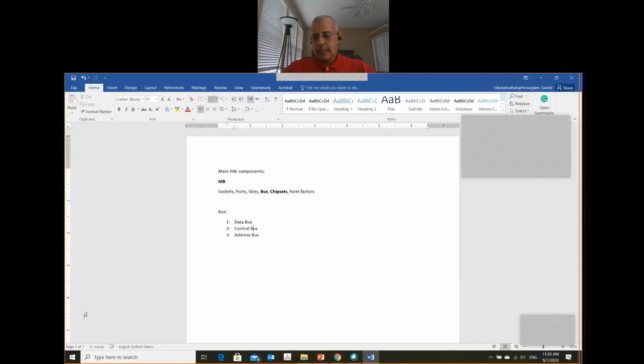Control buses, they define who can read from the bus. Suppose a bus as a kind of path between two cities. So it determines which end can read from this data line. An address bus determines where information should be sent, and defines the address where information should be transmitted and also where the information should be stored in the memory, in the hard disk drive, and etc.